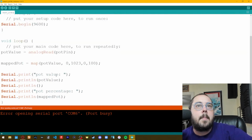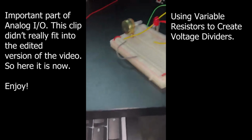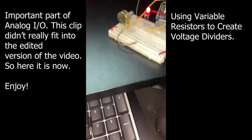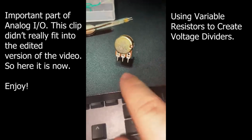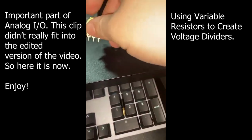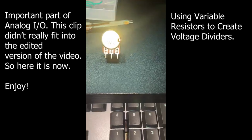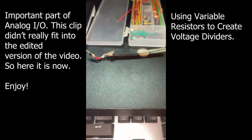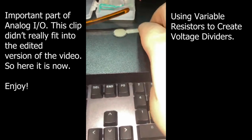So again, this is the core of the code. The code part is very simple. So one thing I want to go with is this is a potentiometer. Again, it has a built-in voltage divider. A lot of components and sensors may do this, and you can usually tell the ones that have the built-in voltage divider because they'll have the 3 leads. This is very generally speaking. Again, I can't speak for every single component out there, but a lot of the sensors you'll use are just the resistor part that changes. You still have to build the rest of it.